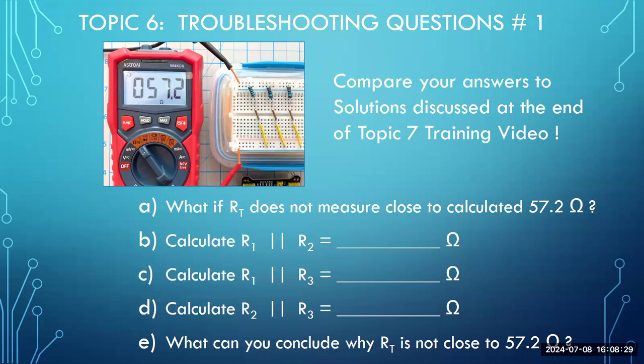the bank of resistors. Remember, the nickname for a set of parallel resistors is called a bank, and the nickname for a series circuit is called a string. So as we look at this, the 3 resistors from the previous calculation worked out to be 57.2 ohms. Now, if you don't recall or didn't watch video number 6, the resistances are for number 1, 100 ohms. For number 2, 220 ohms. Number 3, 330 ohms. So 100 ohms in parallel with 220 in parallel with 330.